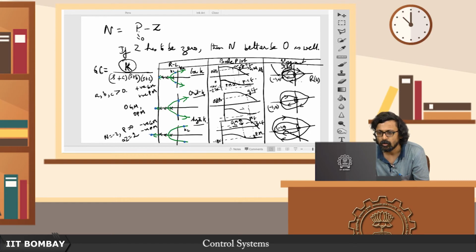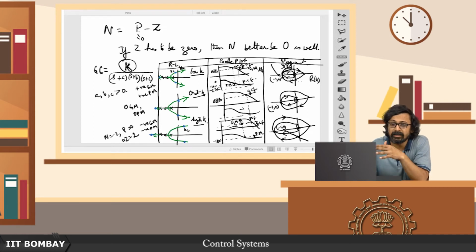So this 1 by this is going to be less than 1, because this point is greater than unity. So 1 over this, which is the gain margin, is less than unity. If you take the logarithm of that, then it is going to spit out a negative quantity. Log of a fraction is negative. So therefore you will have negative gain margin, as suggested by this Bode plot as well, in decibels. So that is what negative gain margin means, we are talking about in decibels.